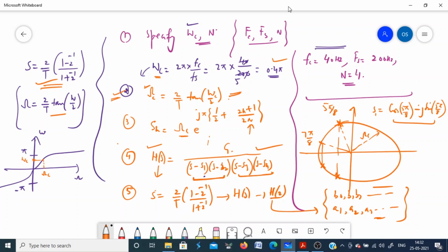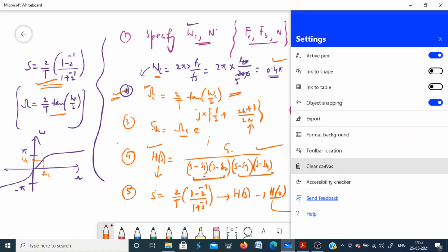If you use a Butterworth filter to eliminate this baseline frequency, you have to pass only the high frequencies and reject the low frequencies. So you say that the filter must have a response like this. The cutoff frequency now is 0.7 hertz.